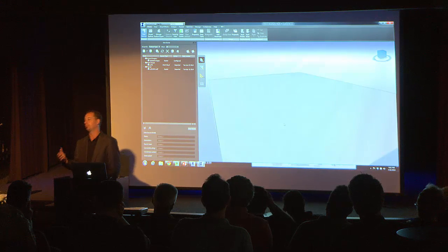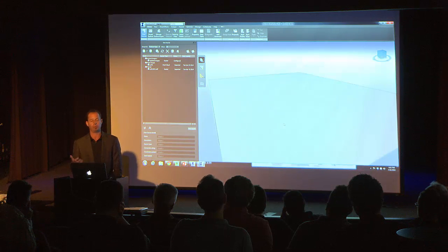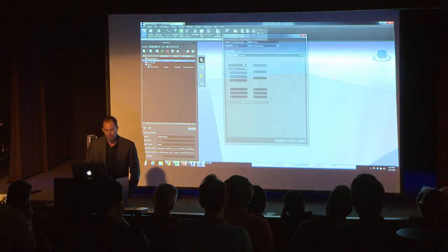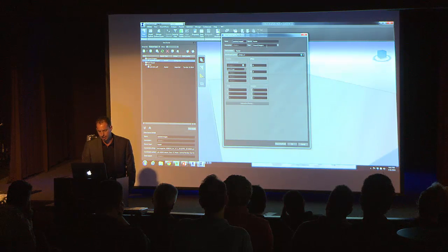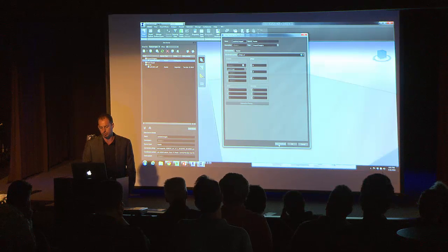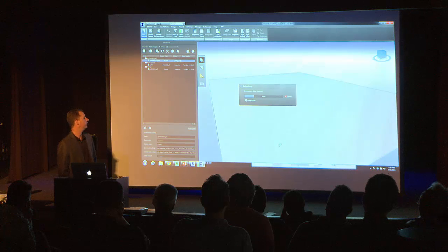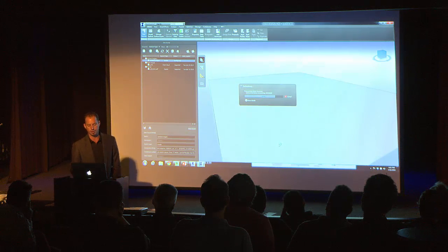What happens is in the program, you're reluctant to use it a little bit because you keep bringing this in and it's not showing up. Every time you bring in the data, all you have to do is either refresh it, or just double click on this, and it will open it up and it's looking for more information. In this case, I already have the images. All you have to do is hit refresh, and now it's going to drape the images directly on top of the surface. But you just got to make sure you don't miss that step in order to refresh the data as it comes in.